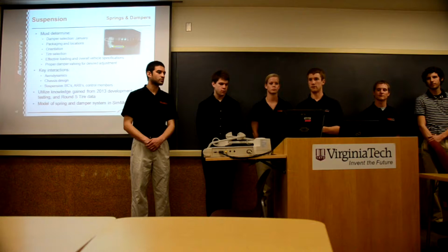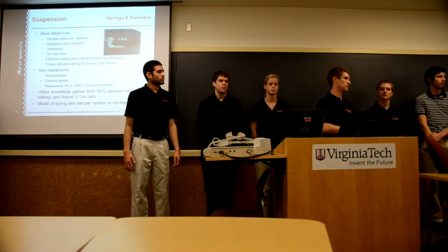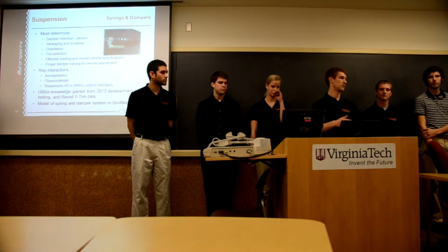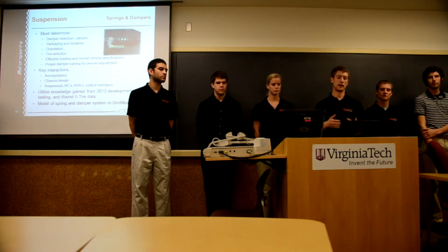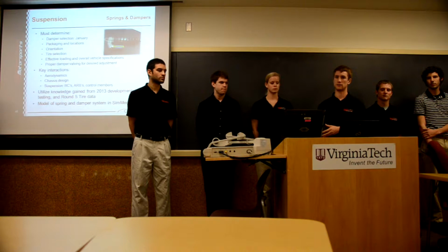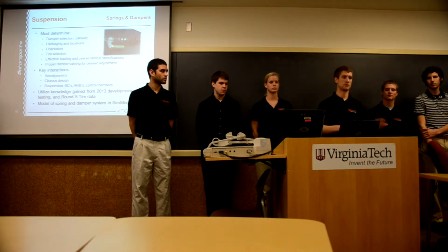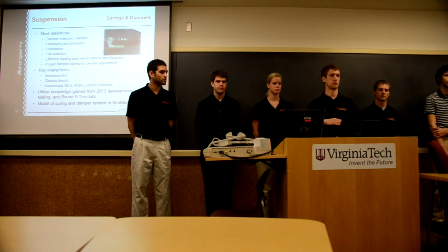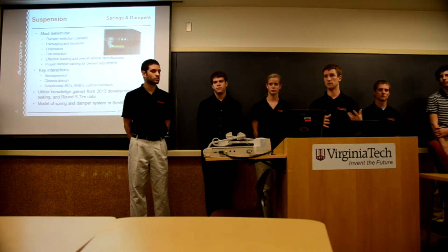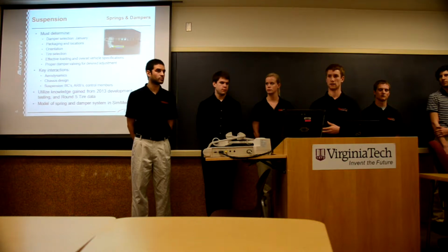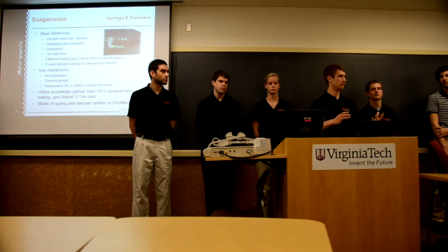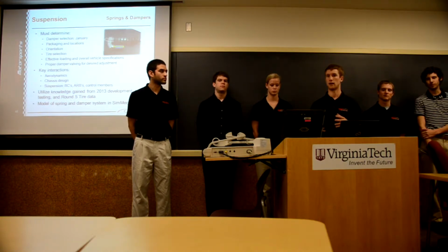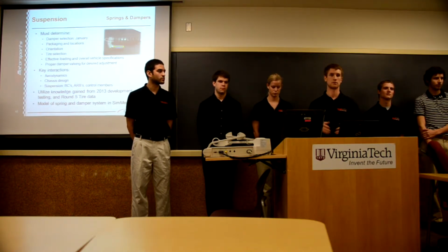So for the vehicle, we need to determine damper selection first. This will define a lot of the parameters in the suspension design overall, especially with our installation ratios. Likely, I'm going to continue using the Öhlins TTX25s, revalved just like what we did on the '09 dampers from that year, which we're using on the 2013 car. This way we can use current development data directly in that model. And the valving should be reasonably close, and if we need to swap in and out for reliability or any issues that we have with dampers, we can do so.